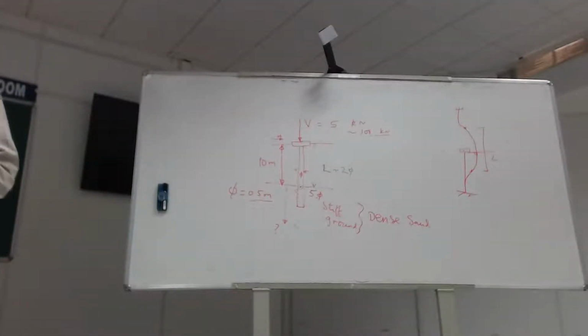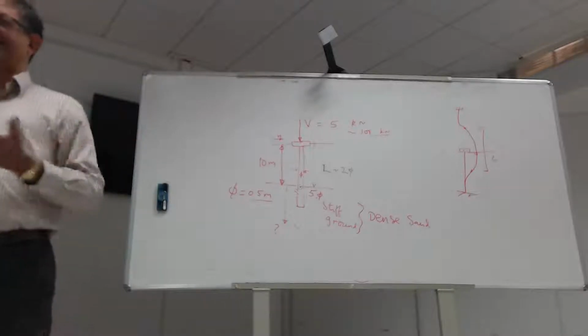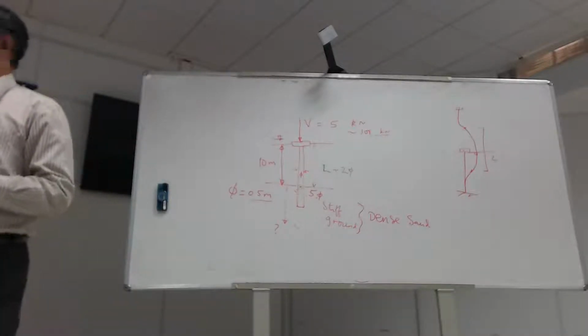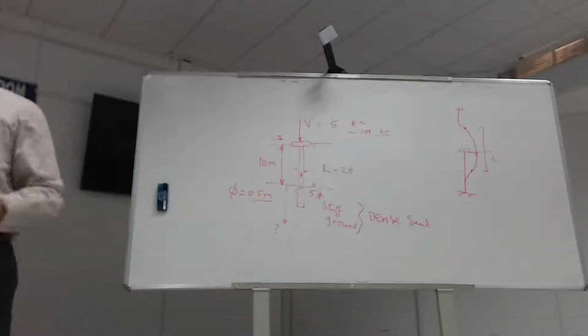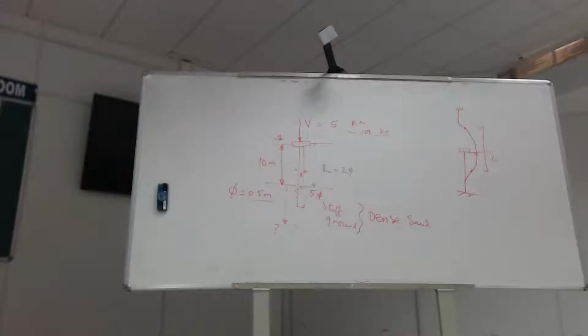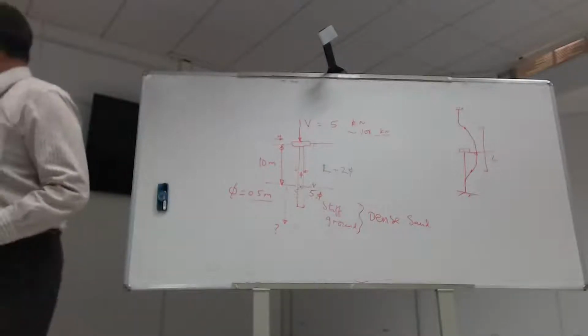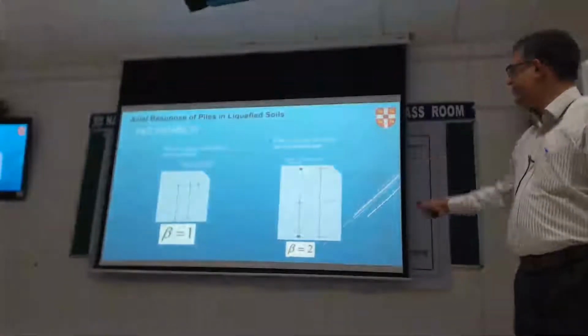No calculations needed. Cambridge undergraduates are particularly poor at working out the algebra, so we tend to give them graphical ways of drawing these things. Once you get the mode shape idea into your head, because we're coming from dynamics, this makes more sense. Working out Euler's buckling loads is exactly the same eigenvalue calculation you do for your dynamic analysis.